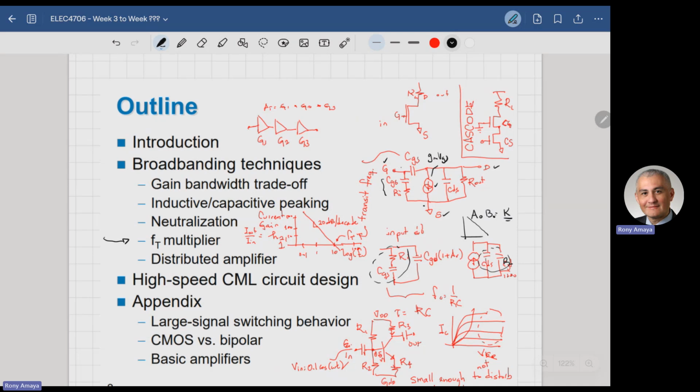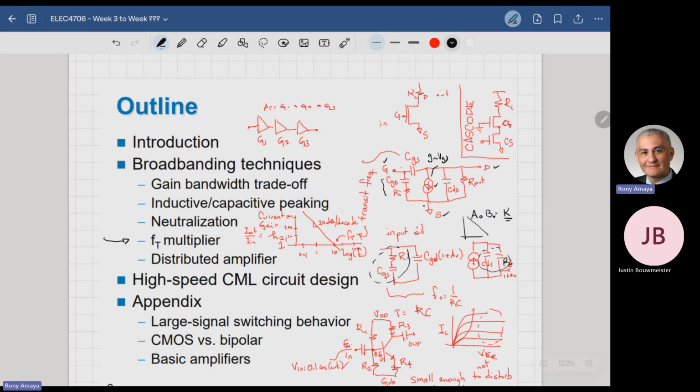So I would always want to deal with the lowest possible substrate or technology node that I possibly can. Why? To give you some references, if you do a design in a 65 nanometer technology, that's about $250,000 US per fab cycle. If you go to a 45 nanometer SOI, we're looking at close to $1 million, maybe $900,000 US when it's all said and done. And if you go into a 3 nanometer process, it's $10 million or more. That's a lot of money, right? So you don't want to.